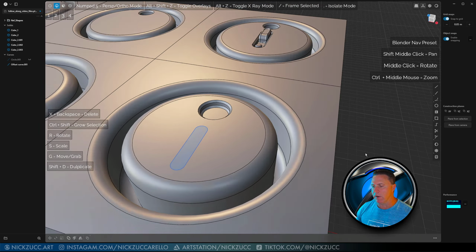All right, I'm going to hit Undo, and I want to show you something else. I'm going to select this body. I'm just going to tap H, and that will hide it. Now, let's select this curve. And what if I want to use a thing that is imprinting these edges on there? So imagine this being something that is going to give us these lines that we see here that we can select. We want these lines on here to do some operations on there.